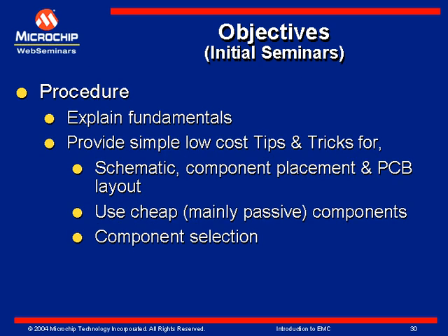And how do we go about it? First, we'll explain all the fundamentals. Then we try to provide you simple, low-cost tips and tricks for the schematic, component placement, and PCB layout. We mainly use cheap, mainly passive components. We'll also explain how to select components. You may use the same capacitor, but what type of capacitor and what value you use may make a big difference in EMC behavior.